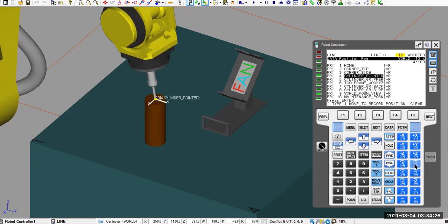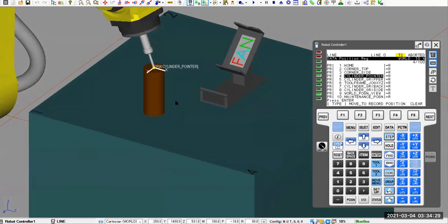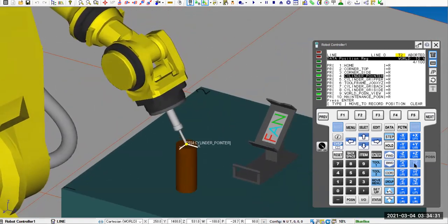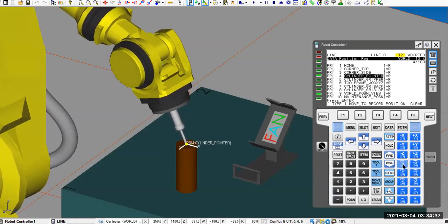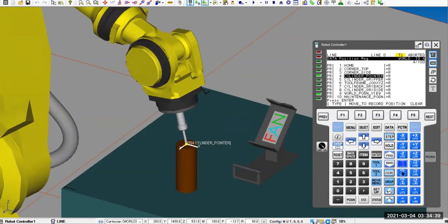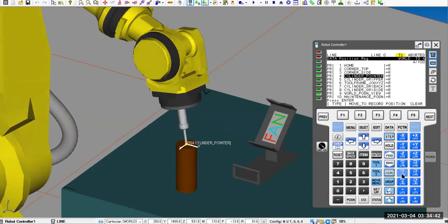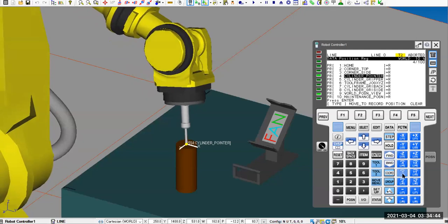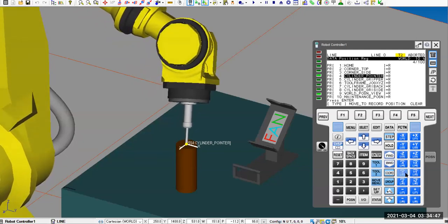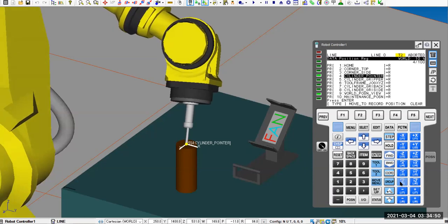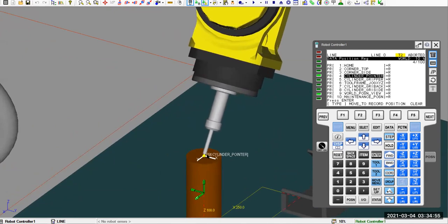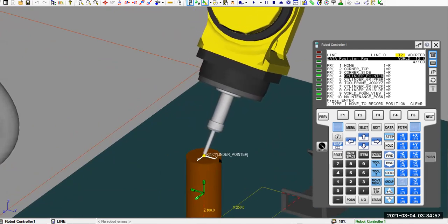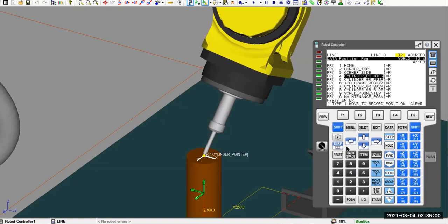You can see here, the robot rotates, right? Just like what we talked about before, it rotates but the TCP stays there. That's negative, that's positive. And then if I rotate around Y, same thing. It just rotates around, and the TCP stays there. And rotate around Z, you can see here, it rotates and stays there because the robot knows that's the center. It doesn't move away. All right, so this is a TCP being set up.